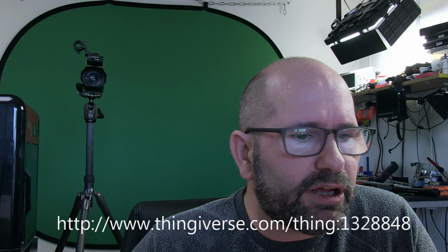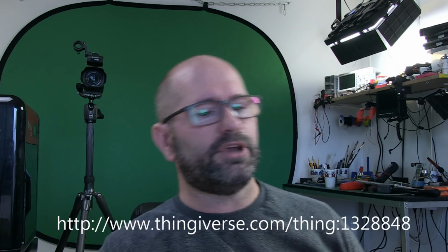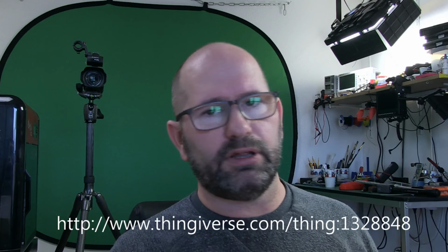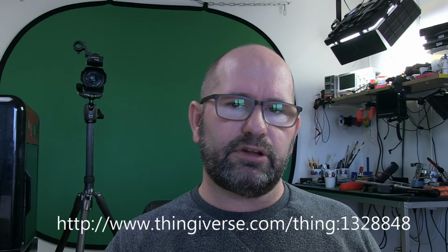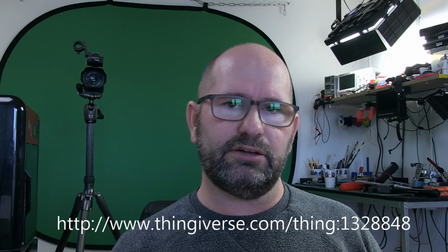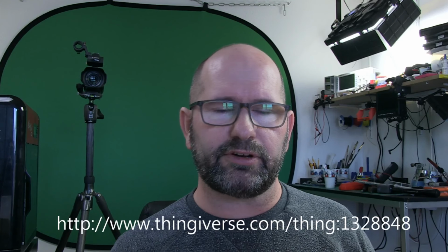I have the original E3D V6 mounted on my Pro. I recommend the profiles from the original Prusa i3 Mark II for Simplify3D. Just retraction needs to be adjusted. Yeah, the retraction needs to be around 6 millimeters. So your retraction settings need to be around about 6 millimeters.